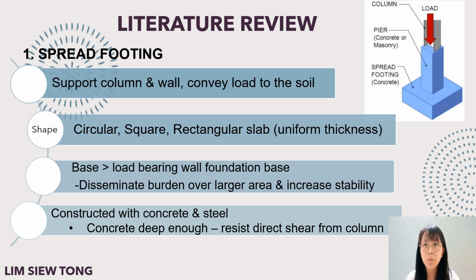The base of the foundation is made of concrete, a reinforced concrete member, and spread footings are constructed with concrete and steel due to their design. Concrete for the spread footings should be deep enough to resist punching and direct shear transfer from the column.